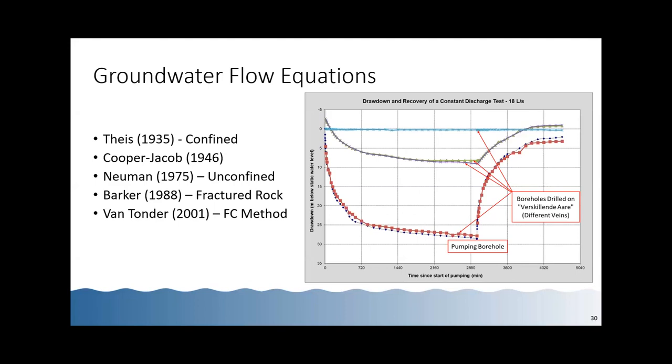If someone says, you know, they found new groundwater, this was a test pump that we did. Only one of those boreholes on this graph. This is now a linear graph, so it's not on a semi-log plot. Only one of those boreholes was being pumped for the test pumping session. The other 4 boreholes that are on the graph are all monitoring boreholes. And we can see one right at the top of there didn't respond to the test pumping at all. But in fact, the other 3 boreholes all responded quite clearly to the test pumping. And in this case, we know if we use this borehole for production, it's going to impact this, abstract this borehole, dry up those monitoring boreholes.